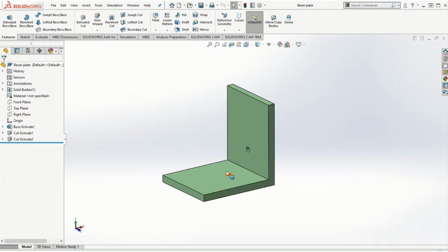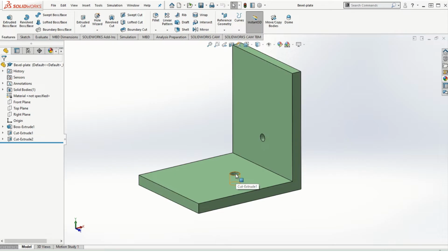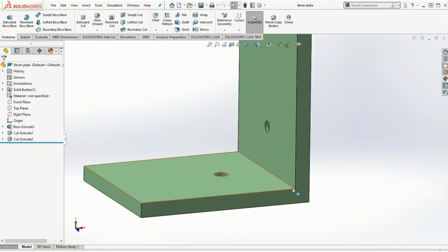In the interest of time, I have already created the plate with the holes as per the shaft diameter for the bevel gear and the pinion assembly. So remember, the pinion is 3/8 inch diameter, and half-inch shaft diameter for the gear, so that has already been created at appropriate distances so that a perfect assembly can take place. So based on the dimensions as shown in that previous slide, you can design your own plate and then drill the holes accordingly at the distances as required based on the mounting distances for both gear and the pinion, as well as considering the hub width for both the gear and the pinion.